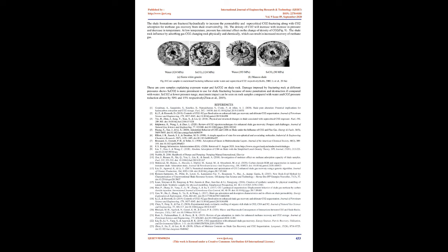A supportive graph, Fig B, for previous results shows reduction in axial strength and Young's modulus. This degree of reduction is influenced by geoenvironment characteristics of shale formations, CO2 phase, adsorption pressure, interaction time, etc. This study is also important to understand borehole stability. It shows changes in stress and strain conditions of shale under CO2 adsorption, A, Yan et al., 2017, B, Liu et al., 2018b.